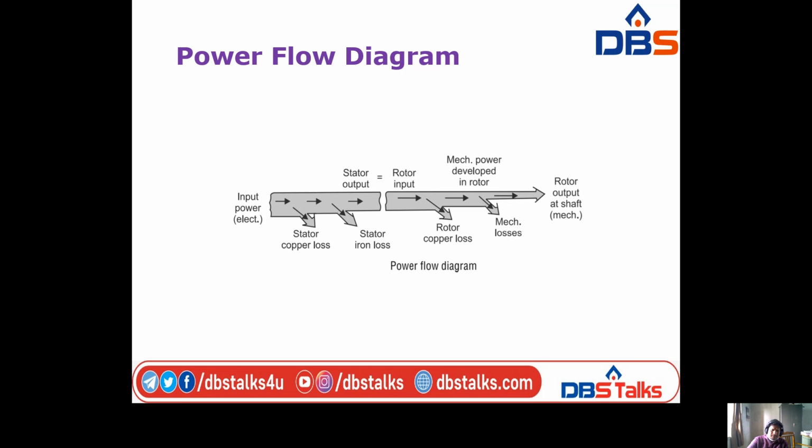From this power flow diagram, you can also easily determine the mechanical power developed, and the stator output, which is the rotor input, and also the efficiency. That means we have to calculate the individual losses. Look at the picture clearly.